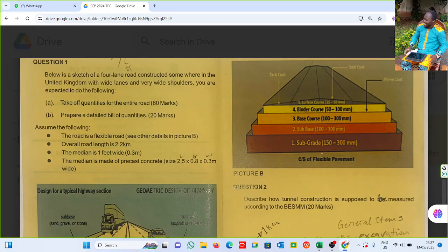While the sub base assists in load spreading, and can also act as a temporary road for construction and assist in subsoil drainage. While the base course is the main road layer of the structure. While the binder course supports the wearing course and also protects the road. While the surface course provides a skid resistant surface and waterproofs the pavement and withstands direct loading of traffic.